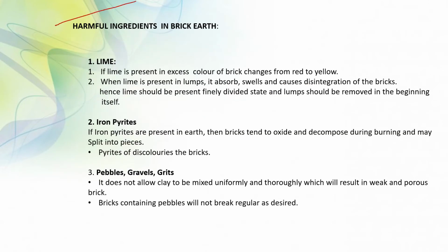Then, harmful ingredients in brick earth. Number 1, lime. If lime is present in excess, color of bricks changes from red to yellow. Number 2, when lime is present in lumps, it absorbs moisture and causes disintegration of the brick. Hence lime should be present finely divided and lumps should be removed in the beginning itself.